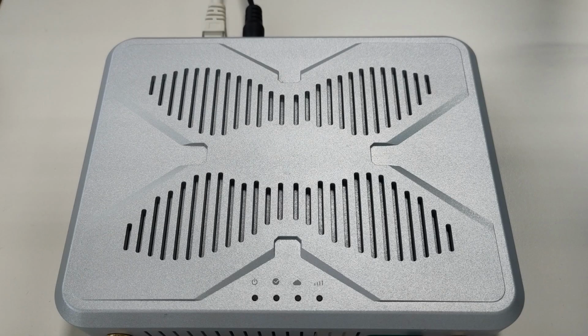In this video, we will present the CMT700 Web UI and its features. First of all, ensure that the device is connected to a 12-volt power supply and Ethernet cable. It is also possible to directly supply it with a PoE plus capable Ethernet cable. When the device has a proper power supply, the green LED will turn on.